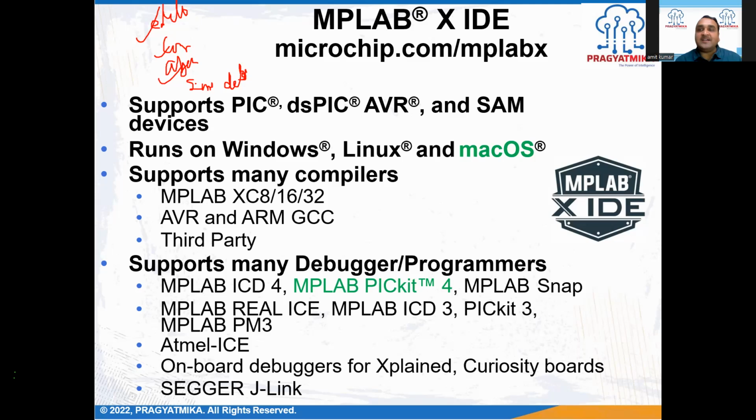That's why an IDE is a single software in which you can run all these tools one by one, seamlessly, because once you are editing the program, compilation is not required. Once you are compiling the program, editing is not required. So they are run one by one through a single shell. And that's why it is called an integrated development environment. Whatever software resources you require for development are available through a single software, and that is the MPLABX IDE. It supports a variety of debuggers also.